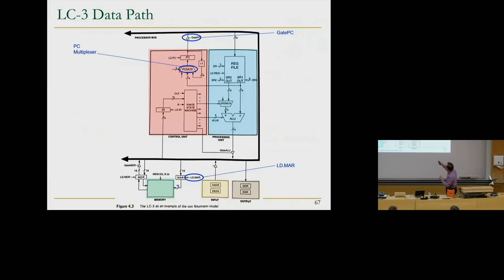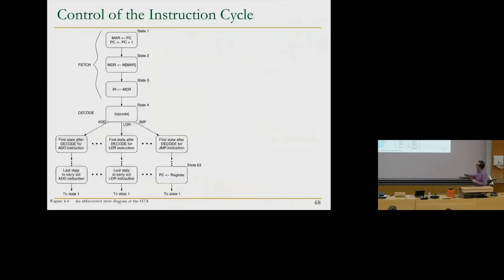So there needs to be a path taking the source register here. You set the control signal during that time so that you select this input, and you ensure that load PC has value 1. You enable that flip-flop so that PC gets written. And the value that's coming out of source register 1 gets placed into the program counter. And we can look at these later on.